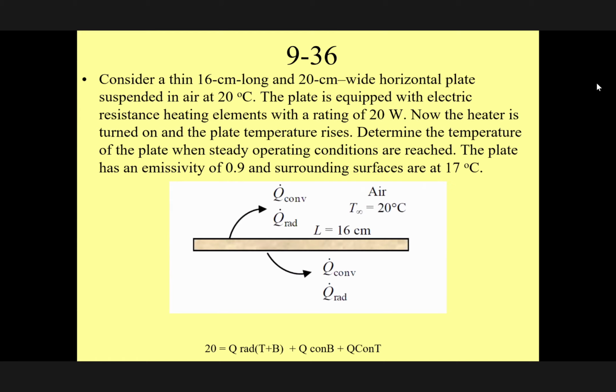And by doing it on a computer, it's very easy because you just add 0.1 degree and continue until your problem converges. But in general, here you have to try to understand the physics of the problem. So it's more like a numerical method, trial and error, in the sense that you have only one equation with the temperature T4, and you just put in different temperatures and find which one is right. So the answer is going to converge.